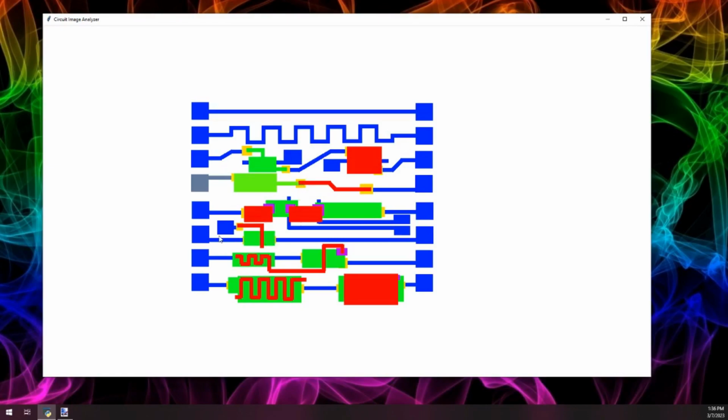Likewise with transistors, here we've got a solid body of diffusion material. And so if I select the metal, if this program were to see this as one body, it would select all of this circuit right here. But you can see when I press the metal, it only selects one side because it recognizes that because there's polysilicon passing over the diffusion, this is a transistor, and that makes it two separate circuits.